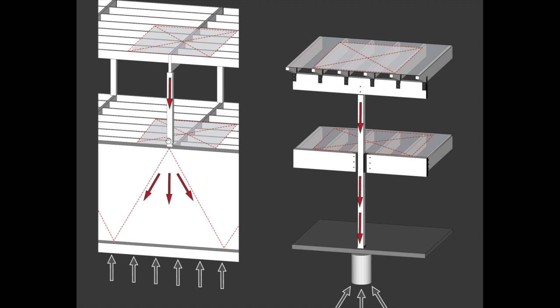So the roof has that, which goes into this column. And then from this point on the back side, we have the tributary area of the floor, which also joins in with the load of the column from above, comes down as distributed through the retaining wall, and then eventually supported by the foundation below. On the opposite side, again, you have the roof tributary load from the girder, comes down into the column, the floor load comes down, you can see then that load is doubled, and then it's resisted by the foundation.